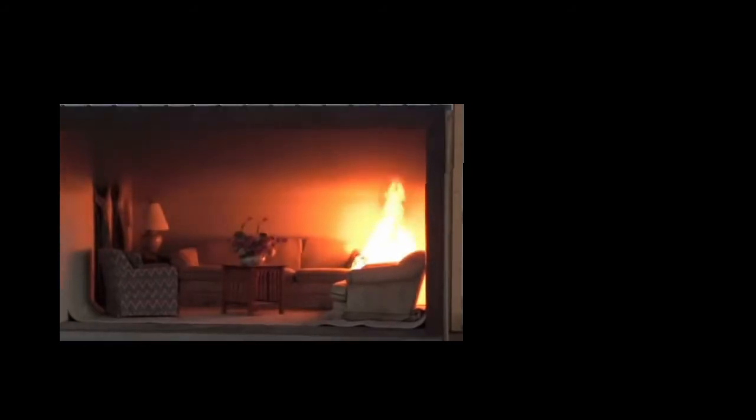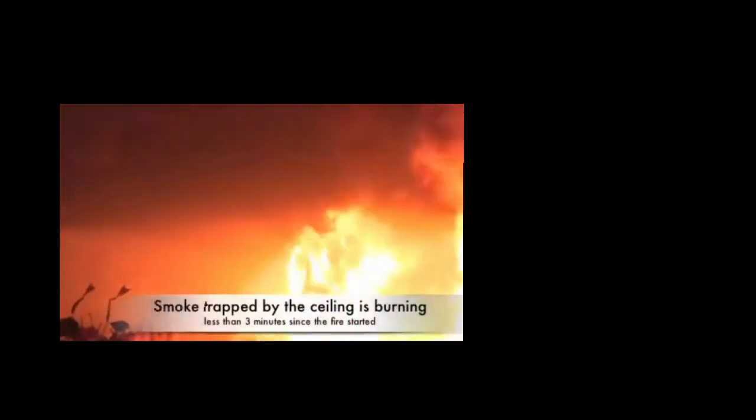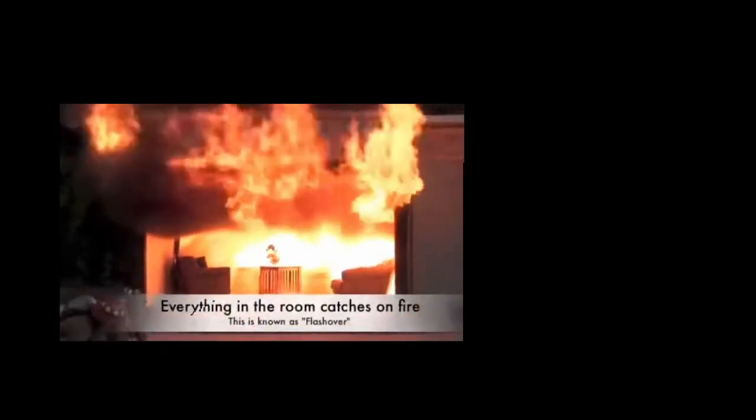carbon-heavy, sooty smoke radiates significantly. And when you hit that 600 degrees Celsius at the ceiling with that soot, it radiates downward. So now that it's smoky up on top, take a look at what that radiation does. It pushes that 20 kilowatts per meter squared on the ground, instantly creating a flashover effect. That's the trigger for the flashover you see there.